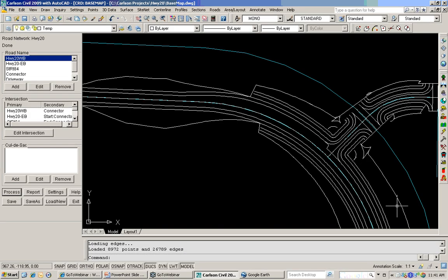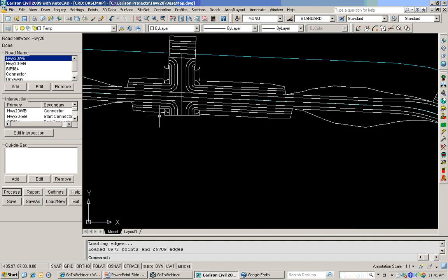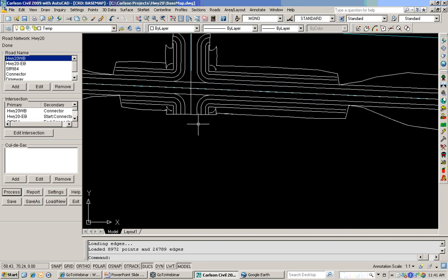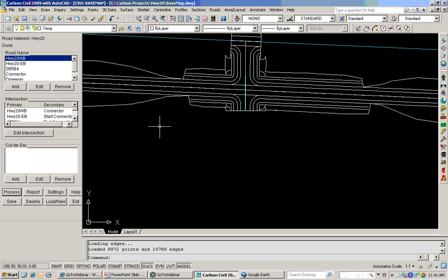So we're getting closer now on what I want to have happen for this preliminary design. Another thing that I want to take a look at is maybe this little area over in here. Now, we talked a little bit about using the template transition to accommodate this. I also want to mention that there's another approach, and that approach is to actually use maybe just a polyline, as we call a template point center line.